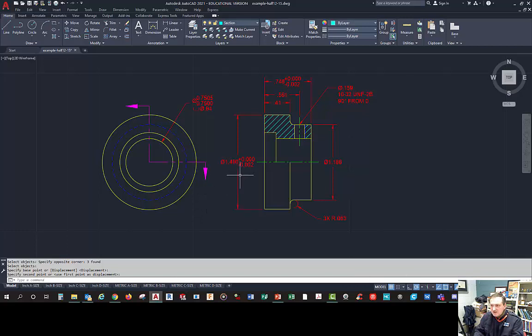So in other words, when I pick on this, it shows all of them, which if you can look past that, it's okay. Here's how you get around that. Figure out what scale you want to use first before you dimension it, and you'll be good to go. And there's some other things you can do. You can go in, you can edit it, you can delete the extra dimension scales, but why? Why don't we just keep it simple?